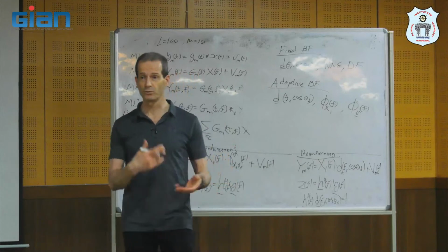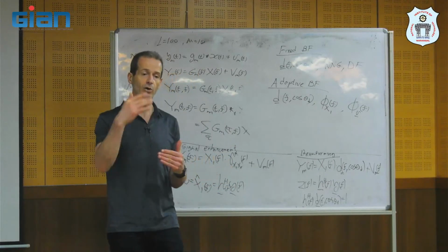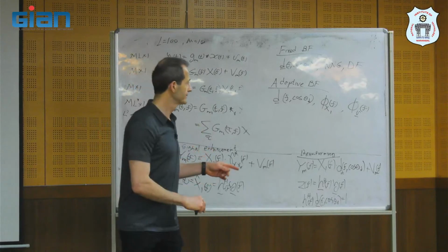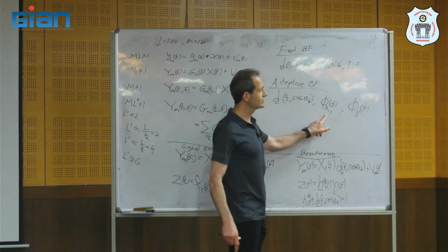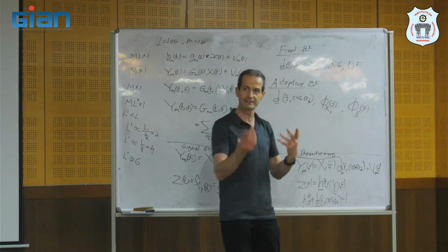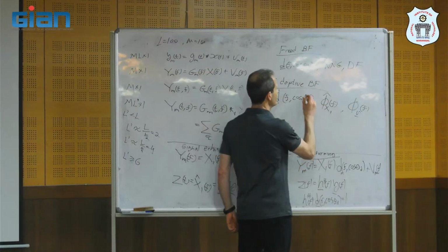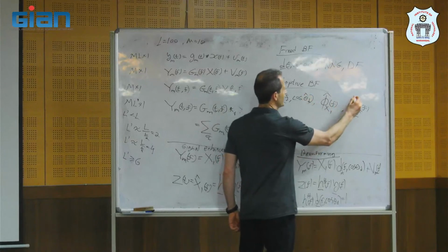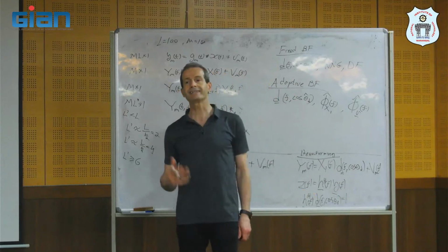So I need to track, to follow, to do adaptive. In order to do adaptive beamforming, I always estimate. I estimate the direction, I estimate the variance of the desired source in the reference channel, I estimate the correlation. I update these values. So all the time I have updated variables.